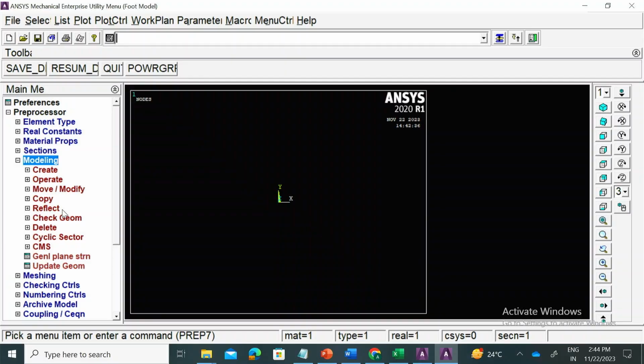And we have applied different kinds of loadings and boundary conditions to it, and we have also understood the overlap operation, where there is a penetration between two bodies, and how the overlap operation makes sure that they are totally integrated in a way that if you had the initial bodies as A and B, then the new bodies created are A minus B, B minus A, and A intersection B. These are the three new volumes which were created through the use of the overlap operation, right?